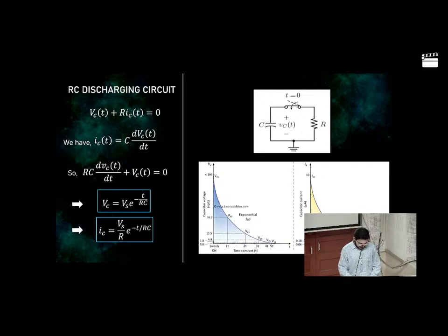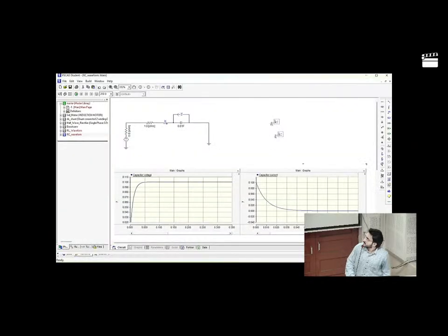And this is a simulation done in the PSCAD environment. As you can see, we have taken a simple RC circuit where the resistance value is 1 ohm and the capacitor value is 0.01 farad, and the source is an ideal voltage source. Now we are measuring the capacitor current as given by Ic, and we are also measuring the voltage across the capacitor. As I just said, the capacitor voltage will be an exponential rise in nature, you can see from the left curve, and also the capacitor current will be decreasing exponentially, which is given by the right curve. So this is done in the PSCAD environment.